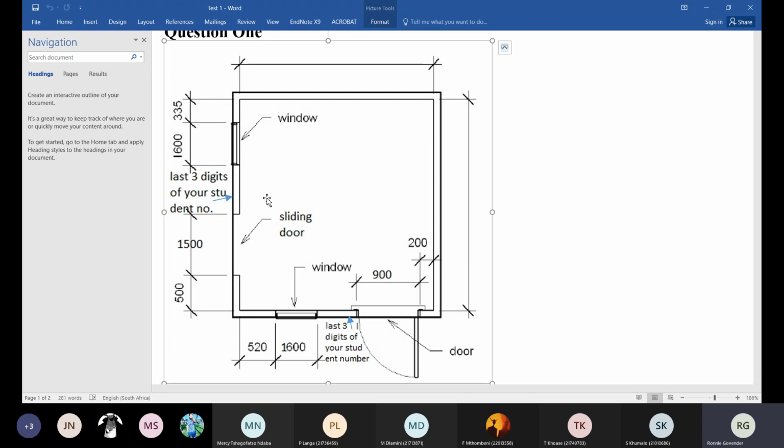And then you take away for the openings, right? For each opening. So the doors, you'll notice, the easiest way to do it is to add both the doors, 1.5 meter wide and 900 millimeter wide. That would have given us 2.4 meters if you add the 2, right? The openings are 2.4 because the door is the same height, 2.1. So I'm going to work out how many courses I'm going to get under the door.